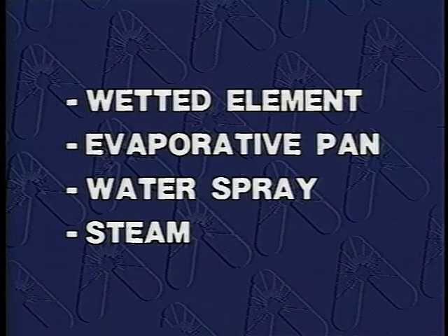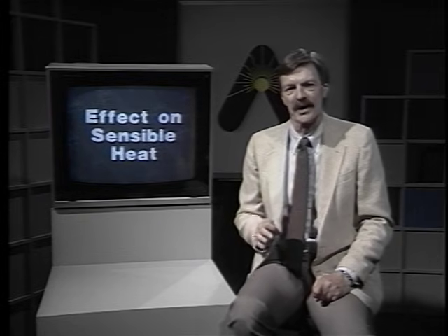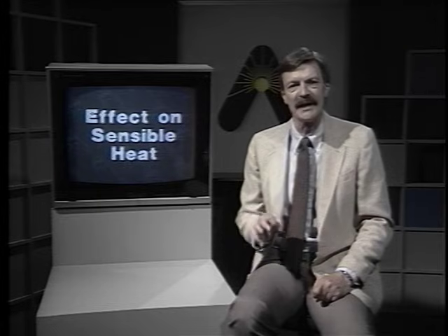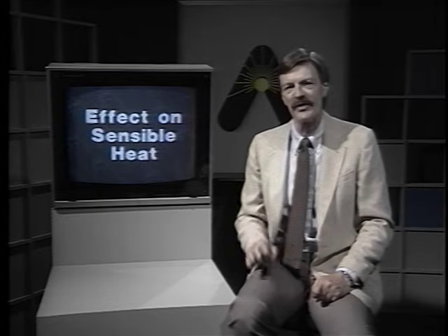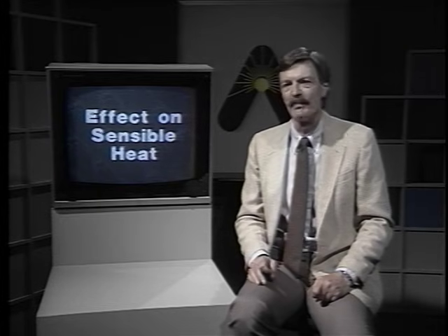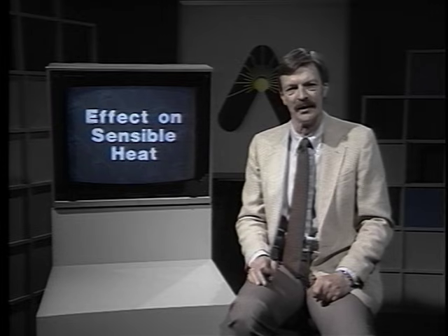By examining the major factors important to effective humidification, we can compare the 4 approaches and determine their suitability to any particular application. The heat of vaporization reduces sensible heat in the air by about 1,000 BTUs for every pound of water that is evaporated.